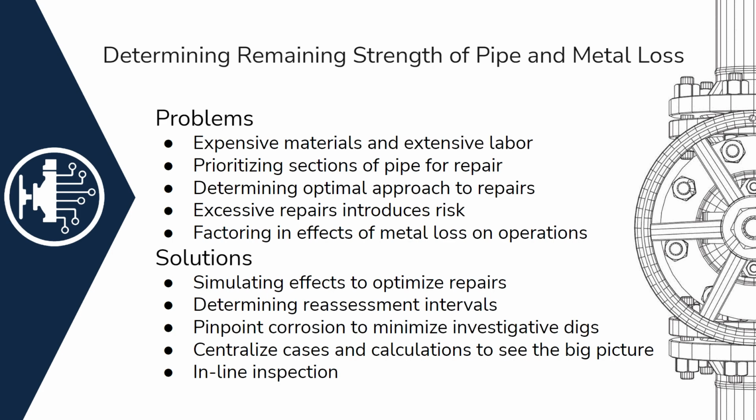Okay, so this is an ugly picture. Let's take a look at it before I take you into determining the remaining strength of corroded pipe. We've got a welding issue, obviously. What do you think they did here? We've got the pipe scratched up, so we've got stress concentrators in there. It looks like they even cut into the pipe to fit it so it comes together, and then they welded those cuts, and you've got splatter all over the place.